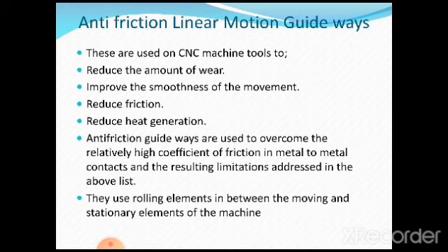How it is in the case of a roller bearing, same one, but these are going to provide the linear motion. In a regular roller bearing, it is going to provide for the rotation of the shafts. So here the rollers can also be used to give a linear motion. That is what he wanted to tell. As in the case of roller bearings, the rollers are guided between the shoulders of the supporting elements with very close tolerances. That means whatever the movement is there, that can be considered with the highest accuracy as far as the positioning is concerned.